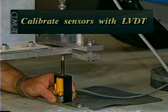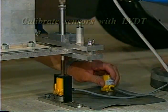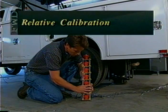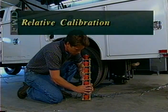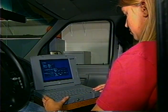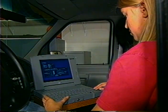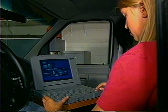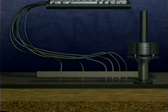Together, calibrating the load cell and calibrating the individual sensors make up the reference calibration. Then, in relative calibration, you compare your sensors with each other. The results of the calibration process are gain factors that you key into your computer. Those gain factors make sure the data produced by your FWD is very accurate. And accuracy is the whole idea of calibration.